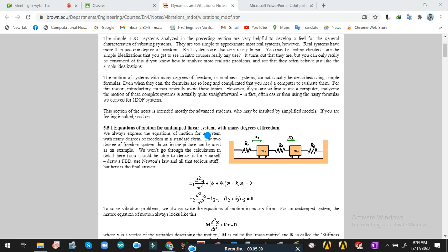For example, if we have a 3 degrees of freedom system, then what will happen? There will be 3 possible mode shapes that a system can withstand. Now each possible mode will be excited at a particular excitation frequency. There will be 3 natural frequencies of that system, and if the excitation frequency is approaching the first natural frequency, then the system will vibrate at the first mode shape.